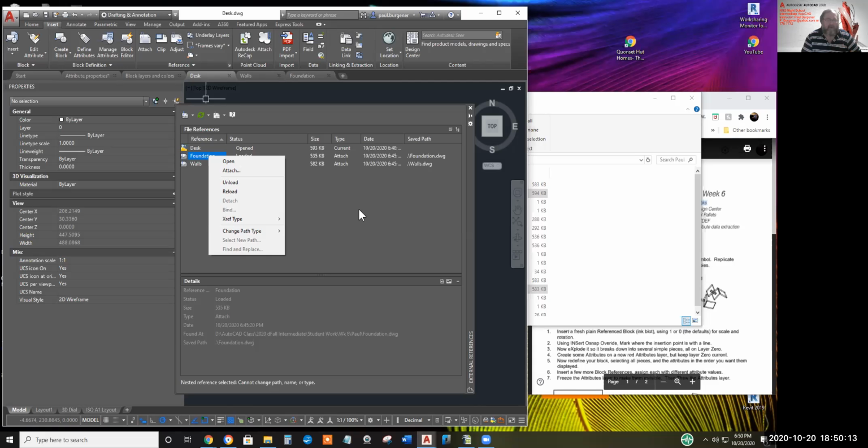I can't remember what the type in command for that is. You can copy stuff from an Xref file. However, whoever owns the Xref file can type in a command that kind of password protects it. You can clip an Xref if you only want to look at a certain room, just like you can clip a viewport.